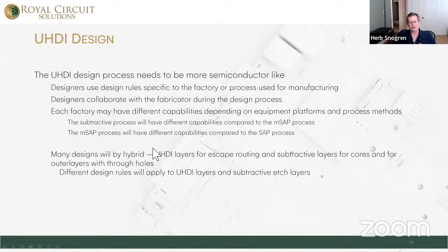So from an ultra-HDI design standpoint, for anybody out there that wants to implement this in their product, they really need to work hand in hand with their manufacturer. Everybody's manufacturing process is going to be a little different. They're going to have different capabilities. They're going to set their process up around some fairly strict standards on what they can do and what they can't do.